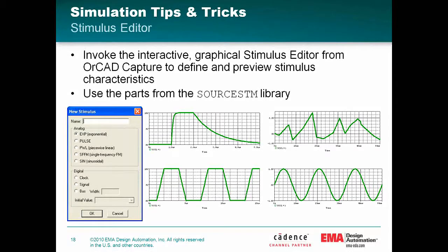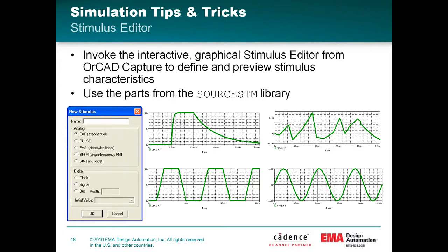Okay, there's a stimulus editor associated with the tool as well. And so like I said, what this allows you to do is create some unique stimulus rather than trying to get an output from a circuit that has some kind of unique characteristic, waveform shaping capability or something. You can actually just create that waveform shape you're looking for in the stimulus editor. It's available for things such as exponential functions, typical sine waves, trapezoids, square waves, most all common waveforms that you're associated with. And it also allows you to do piecewise linear types of things.